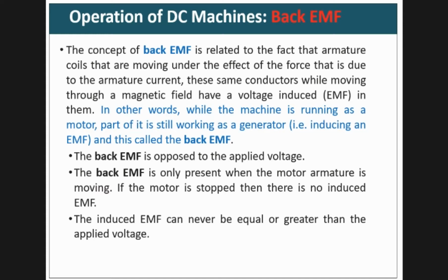So when the motor is working, the rotor coil is rotating in the magnetic field, and due to this rotation it will generate some EMF. That is what we call the back EMF. So while the machine is running as a motor, part of it is still working as a generator as well.